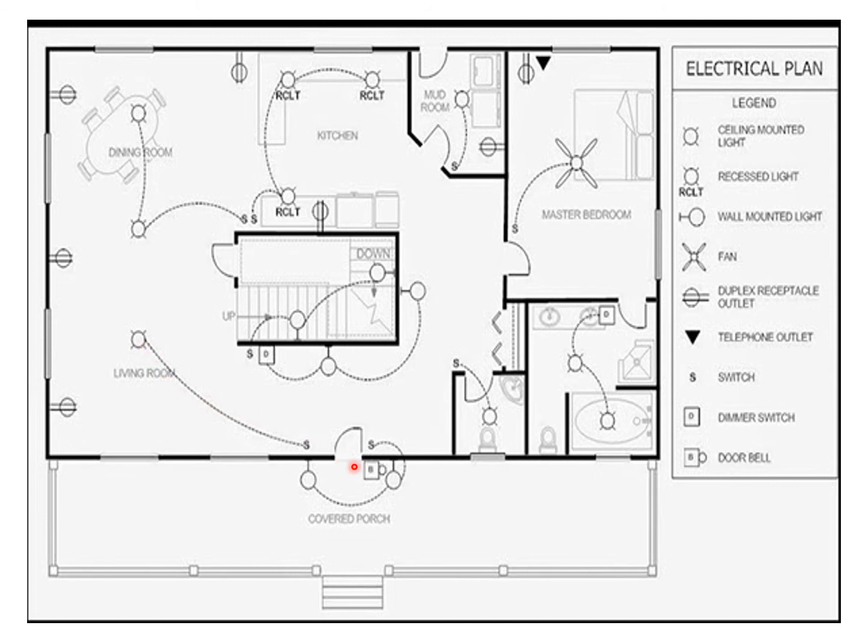So the light is being controlled by a switch here. I have some porch entrance. Then in this case, I may need a dimmer switch. This dimmer light is being controlled by the switch here. Here it is a washing area. So inside that I need a light. This light is nothing but a fluorescent light or ceiling mounted light. It is controlled by the switches. So the dotted line shows the wiring arrangement which has been controlled.